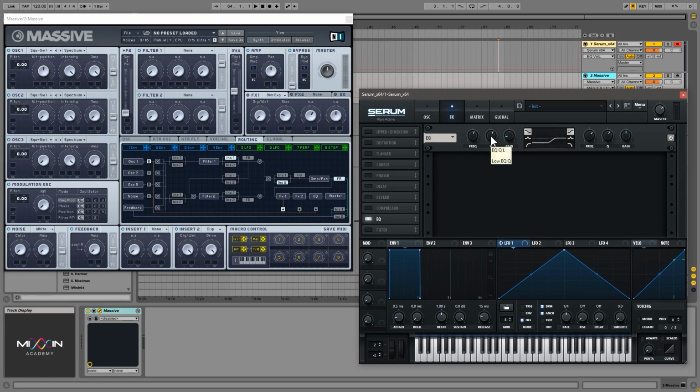And the Q setting will help us determine how fast that change is going to be from the point where we start actually altering those frequencies. It can be really mild, just like that. So this is the shelf filter. Let's try that out. Okay, boosting or attenuating all of those frequencies.